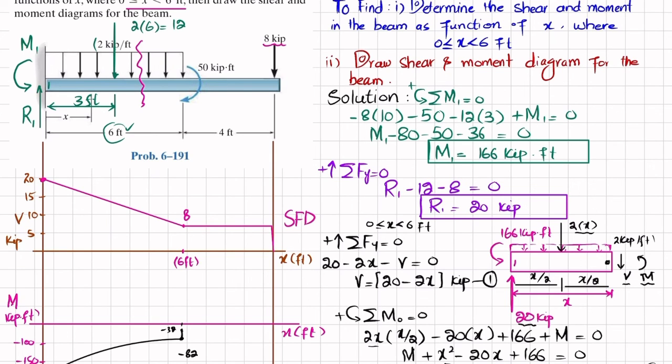Okay. And the last one is the area under the shear force diagram, and you can see this area has height 8 multiplied by length 4. So 8 fours are 32. So minus 32 plus 32 will be equal to 0 at this point. So you will get the bending moment 0 at this point. And we will join these 2 points using a straight line.